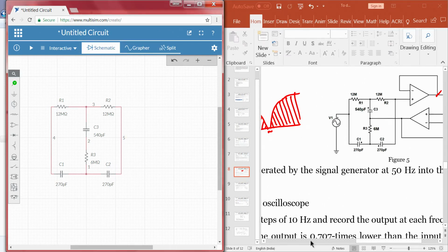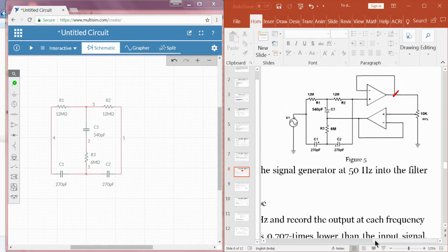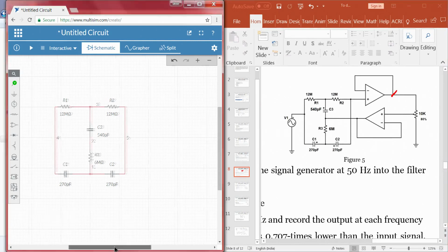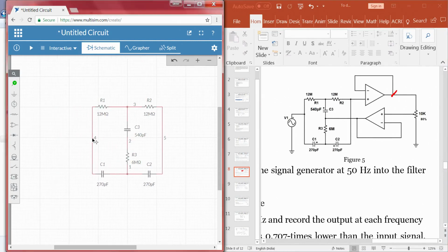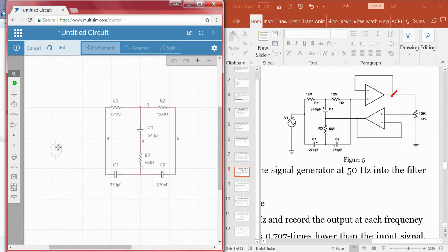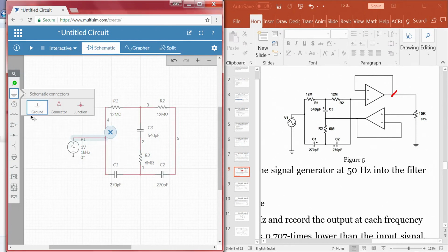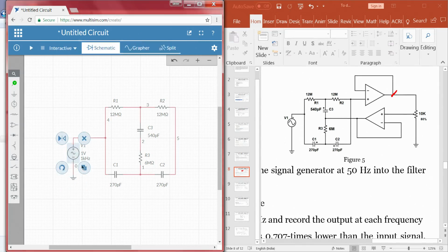Right. So, this looks similar to our circuit, if you observe here. Now, the input should be connected at this point. So, what I will do is take an AC voltage, connect it here, and the other terminal should be connected to the ground. We are thinking of taking a voltage source with an amplitude of 1 volt peak value, so peak to peak we can select it as 2 volts, right. It is relatively easy to understand our output voltage.